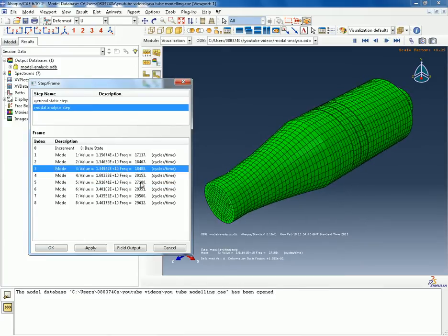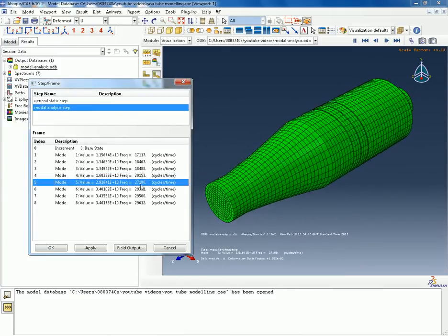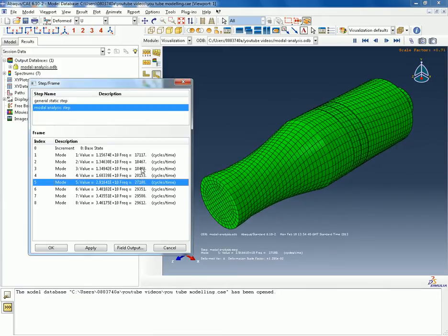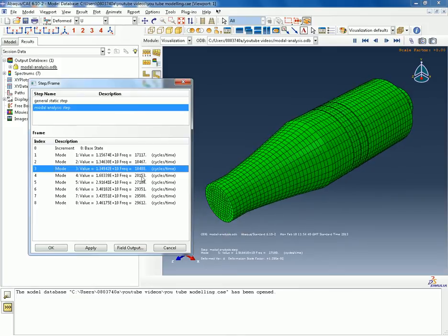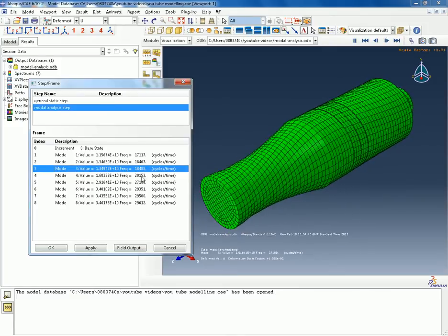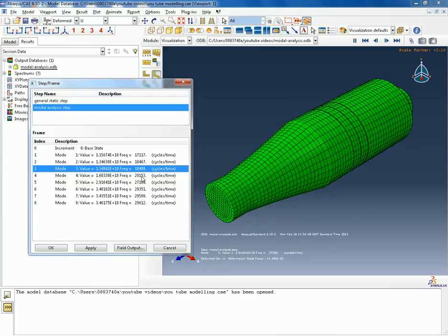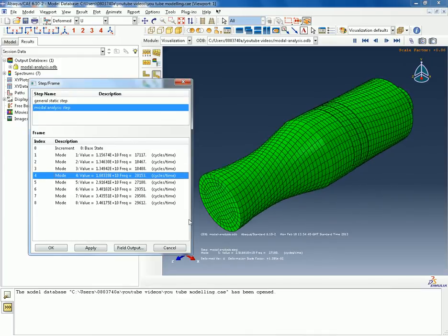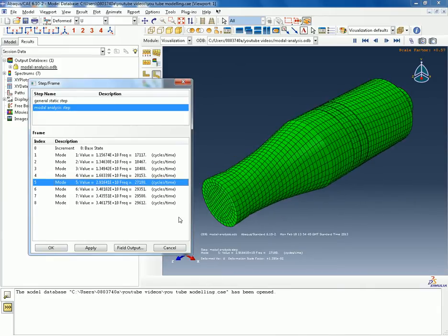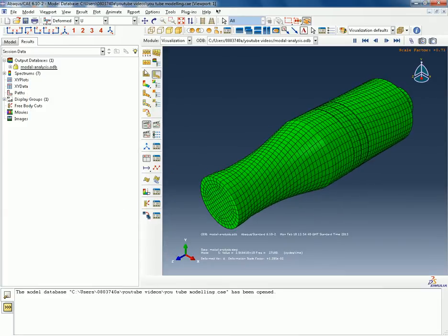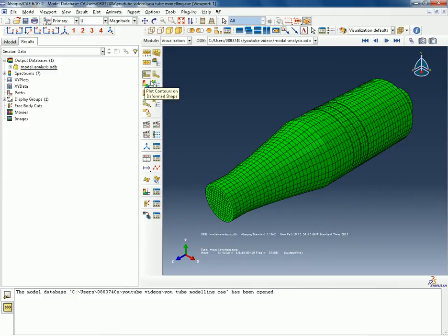Right, the other things we can get from this analysis is the mode shape, and also the precise location of the nodal plane, which is important in case you are planning to hold your transducer. Then the nodal position will be the best choice to not affect the transducer performance. So to do that, we need to create a path along the transducer, the center of the transducer. Then we are going to plot the response along that path.